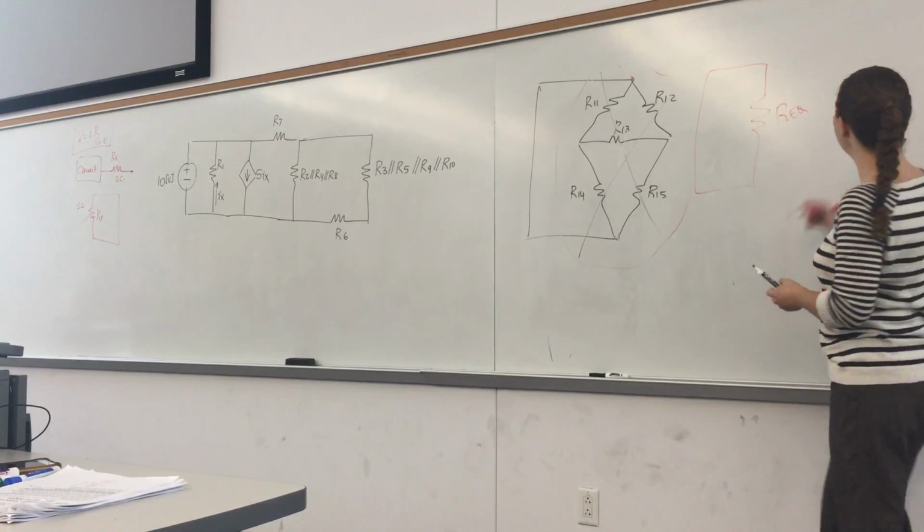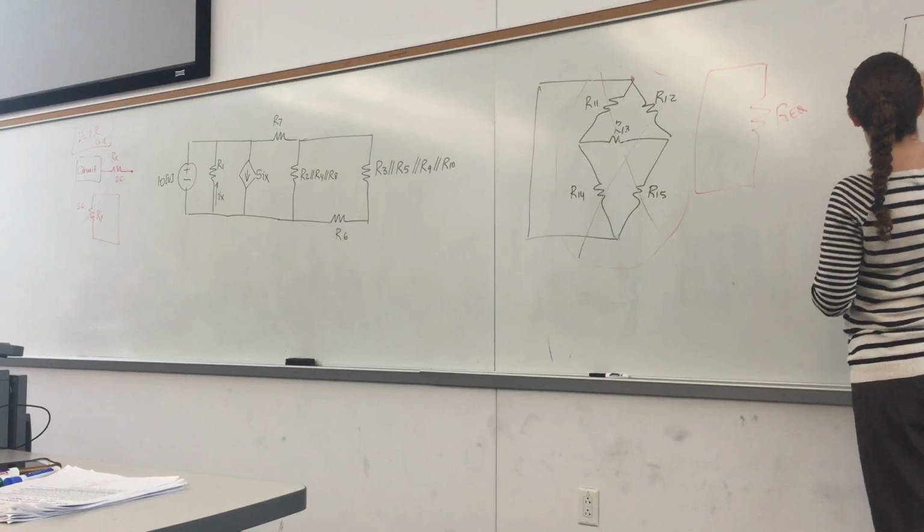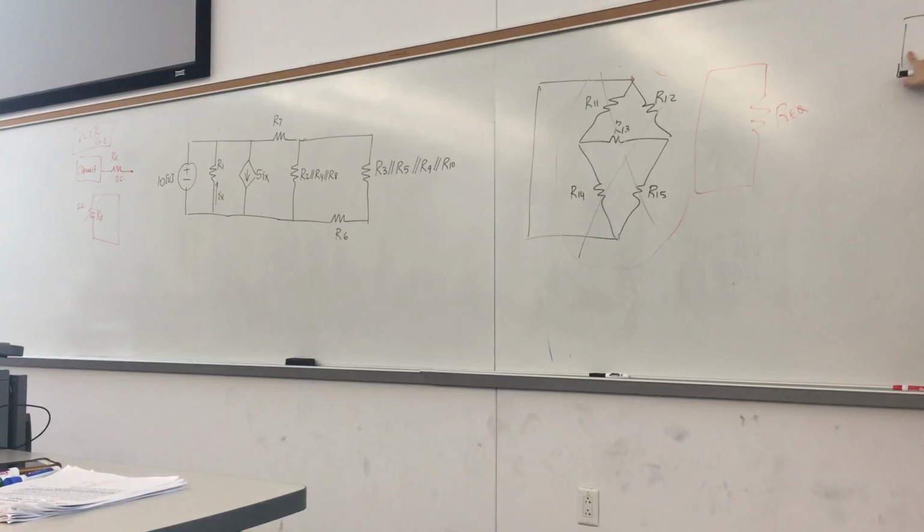It doesn't matter. If you know that a single resistor in parallel with a wire is a dummy resistor, you know that those 2 resistors are also dummy, right? Because added together they will be a single resistor in parallel with that wire. Now you can add another parallel resistor, then another resistor.